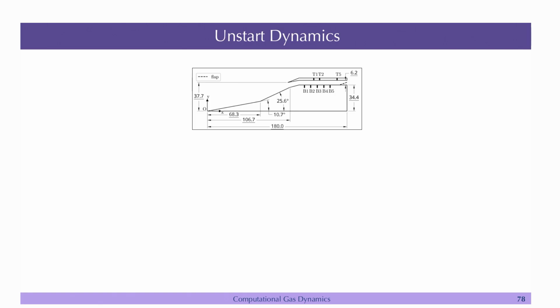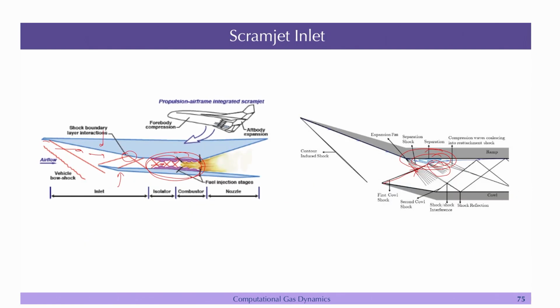Yeah, then you have, let us say you want to, we are interested in unstart dynamics. So, if you look at the picture that we have earlier here, right. So, because of the burning of the fuel, the pressure increases, okay, and basically you have a push towards the inlet, and it leads to something called unstart. Okay, and when there is unstart, the flow will have difficulty getting in. Okay, and that is a dangerous thing, because it may stall the operation, right. So, we want to avoid the unstart.